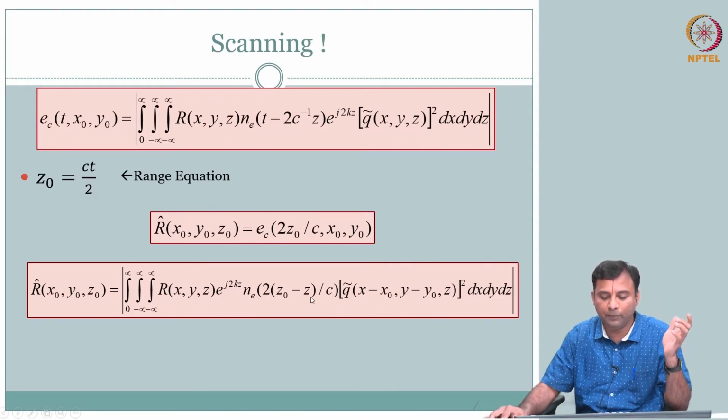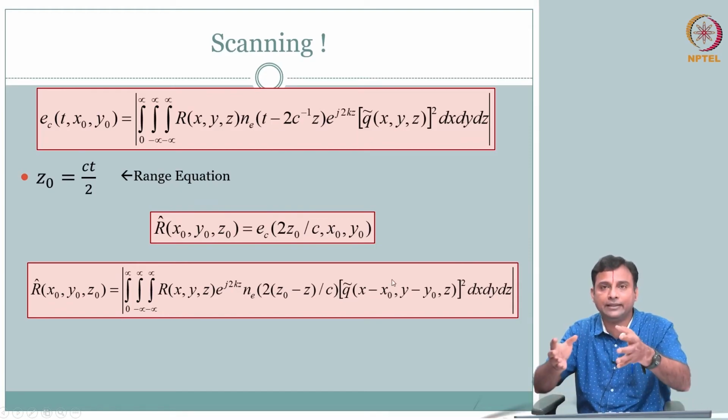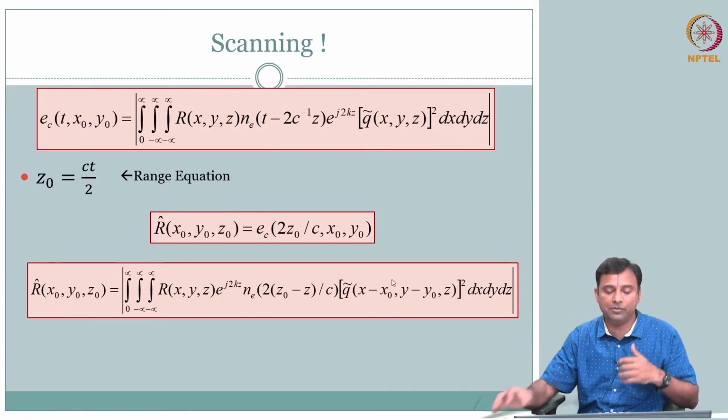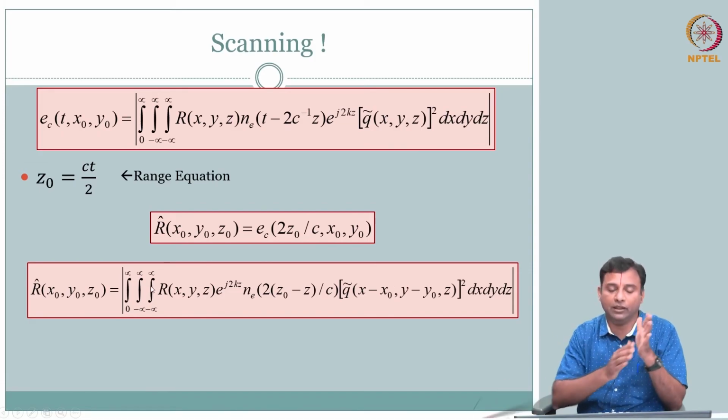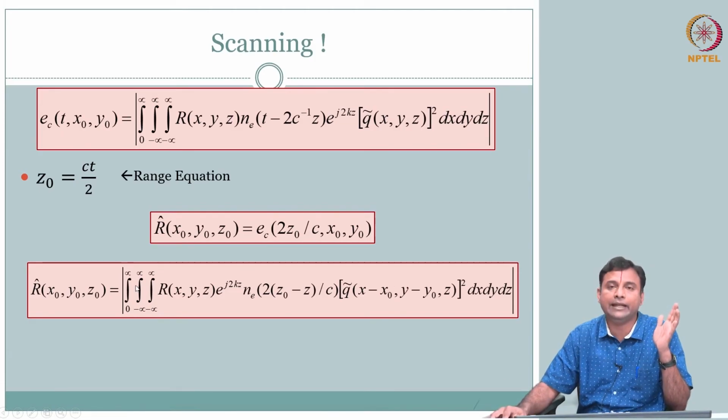The pulse goes through the field pattern and hits a location, whatever the reflection coefficient there, R of x comma y. What goes in hits that reflection coefficient, and that times that quantity is what is coming back. Whatever is falling on the surface, you are integrating and you get a value. This we say is an estimate.